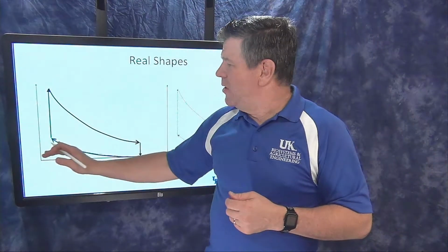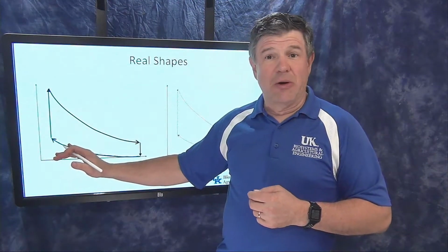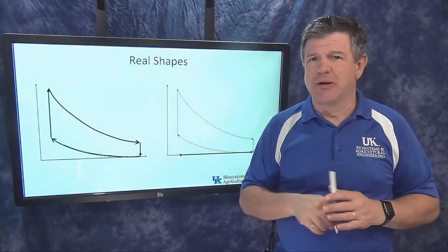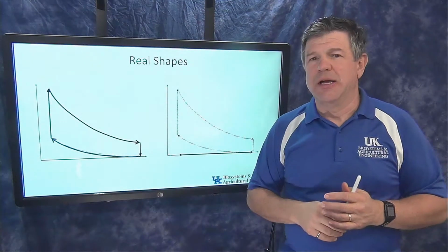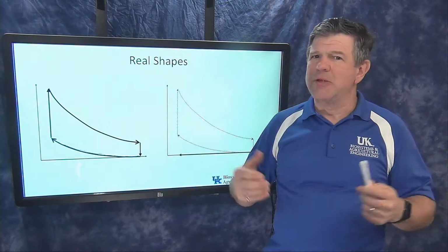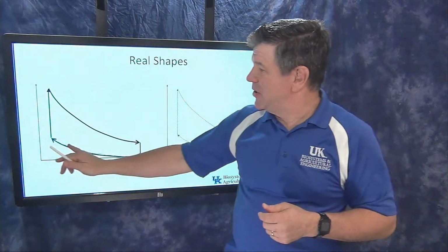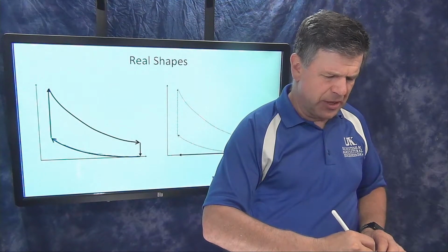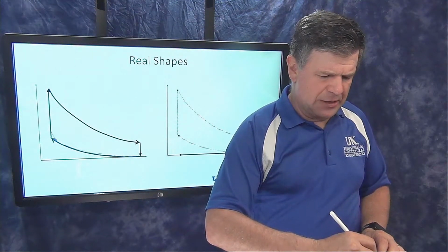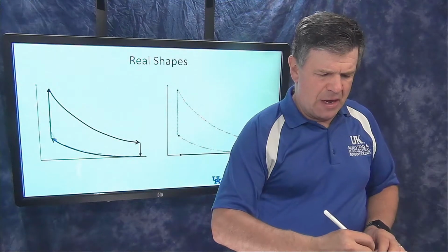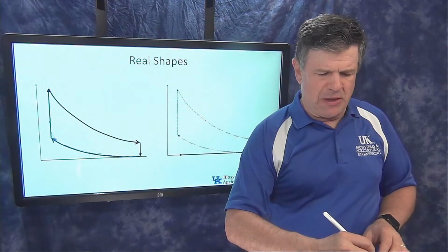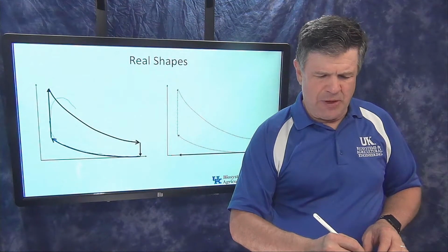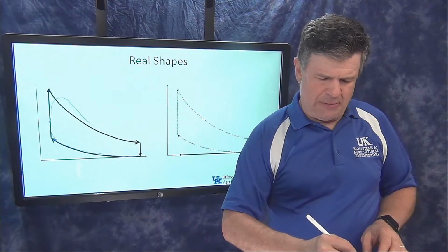And again, we usually start our ignition a little bit early. Remember, we have that spark happening a little bit before top dead center, or the same way with the fuel injection in a compression ignition engine. We'll do that a little bit early. So you're going to see that pressure start to jump a little bit early. So it's going to be more rounded. It's going to deviate from that line, hit this curve, and then that pressure is going to be a lot more rounded. So you're just going to get a rounded kind of thing that looks more like that when it comes down here.